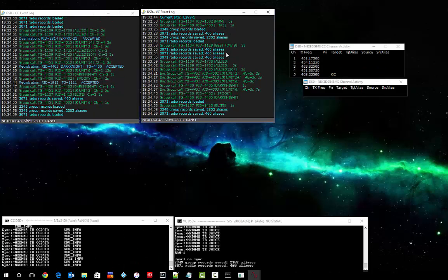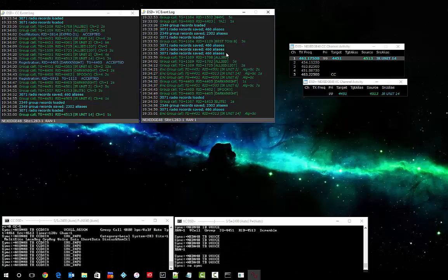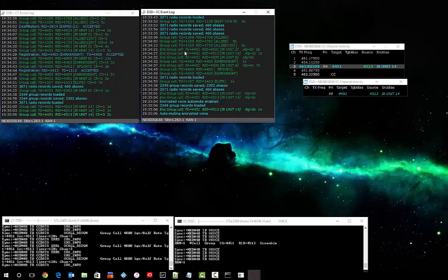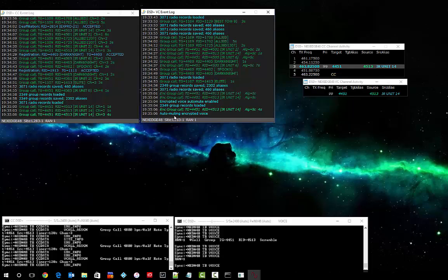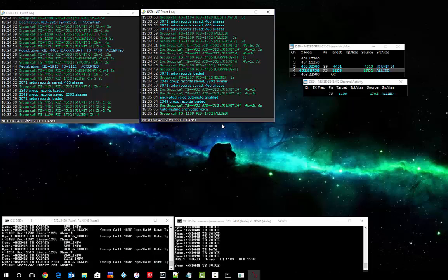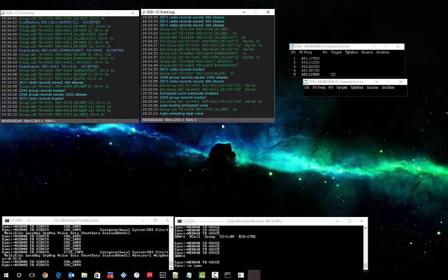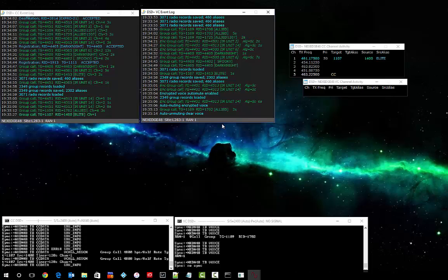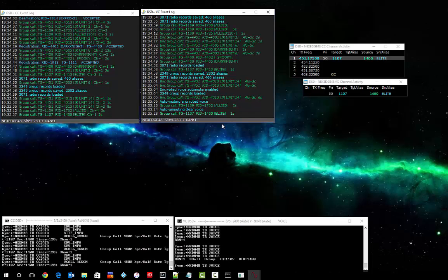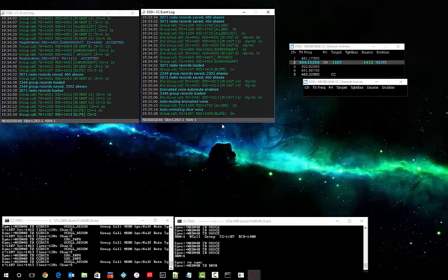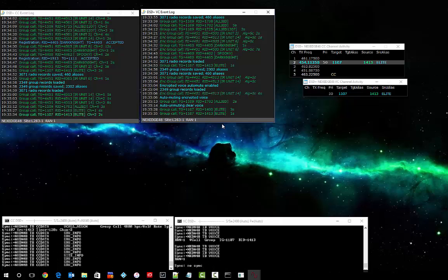And one of the things I can go ahead and do so that I don't have to listen to all that gobbledygook encrypted is if I hit the E key while I'm in the voice control log window, I can see that I can turn on auto muting of the encrypted voice. So if it tunes to the channel and sees they're encrypted, it mutes it. I don't have to listen to it. As soon as somebody else starts talking that is not encrypted, it will unmute itself and I can listen to it. And so that's how you get the newer DSD Pluses set up to actually do trunking.